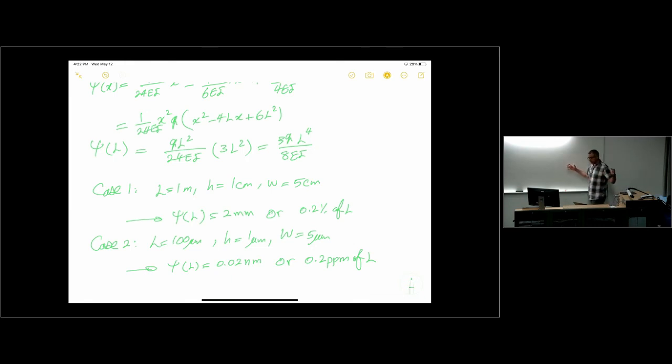So when you shrink it, the lesson here is that gravity is not going to affect the behavior of this beam that much. It's not really deflecting from its rest position that much because of its weight. And this is true in most MEMS devices. In most situations, if you're looking at the static response of these devices, you can ignore the effect of gravity on the initial displacement of these devices.